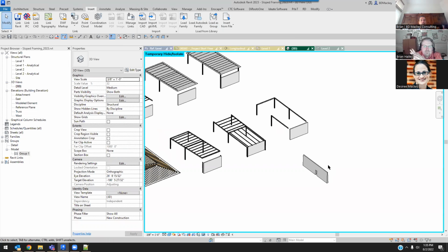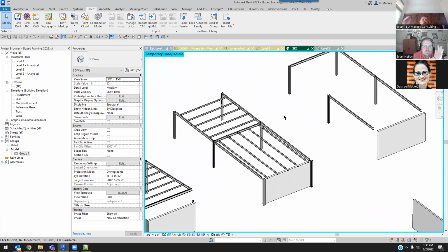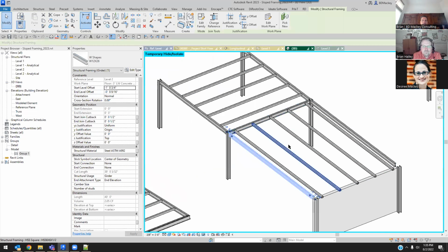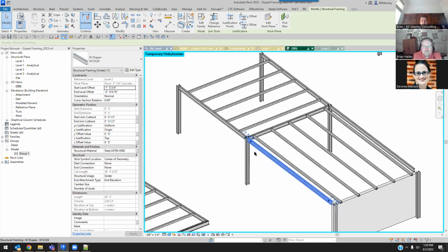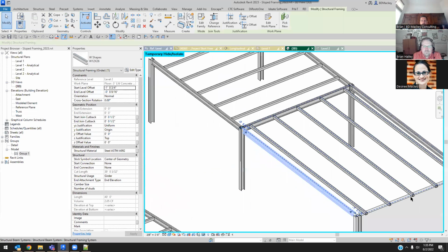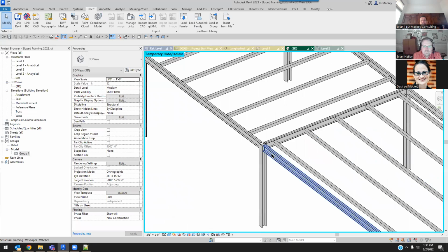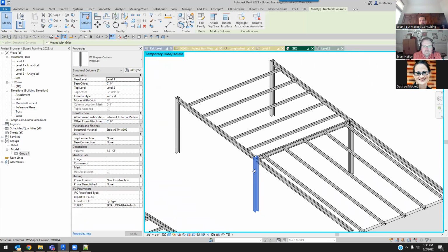So that's one thing that I would always say, honest truth, as a structural engineer, I haven't found groups to be that useful. I know it sounds like something that should do. I mean, groups work really well for architects. They're non-existent for MEP. They just don't work in the MEP world. And in structure, yeah, you can kind of do it, but if this was a typical bay and you were grouping it, do you leave this one member unattached to this column and it's a group, and then you copy it over? So you've got two columns and a giant cantilever that you're just going to place groups next to each other. That might work, but then it's like, oh, I need to move something or adjust something.